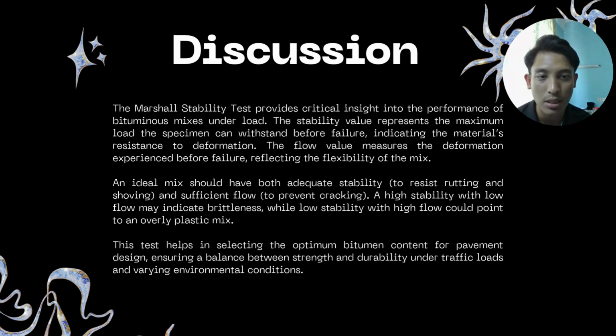The flow value measures the deformation experienced before failure, reflecting the flexibility of the mix. An ideal mix should have both adequate stability to withstand rutting and shoving and sufficient flow to prevent cracking.